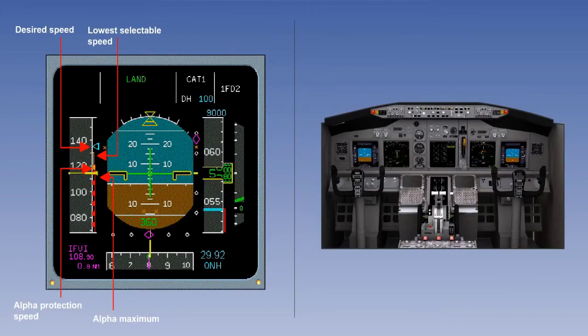Regulations stipulate that in large aeroplanes, the stall warning system must activate before the stall speed by an amount greater than either 5 knots or 5% of calibrated airspeed. It must continue to work until the angle of attack is reduced to at least the point where the stall warning was initiated. The warnings can be in the form of visual warnings, sensory warnings, such as stick shakers, which are fitted to the majority of traditional type aeroplanes,